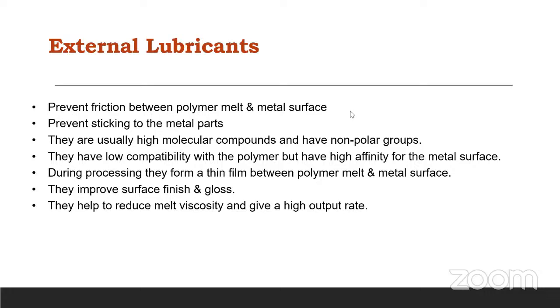If you mix them suddenly in an extruder, surely there will be issues of dispersibility and wettability of your PVC powder. So to make it properly wettable, a prior blending, or compounding, is carried out.